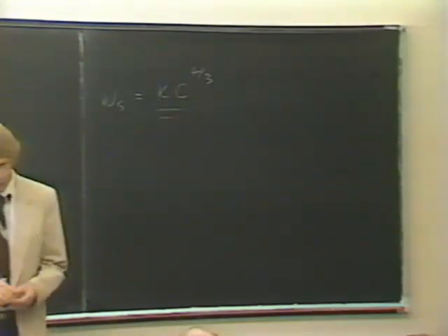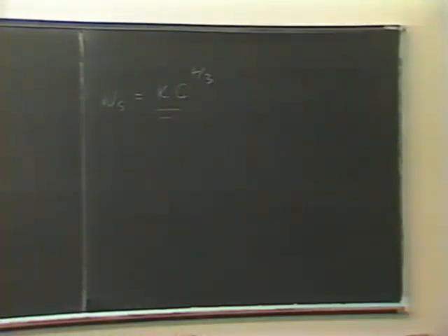And it's probably not too bad, say, in an enclosed harbor, where the breakup of the aggregates by the high velocity gradients near the bed is not a significant factor. But out in channels where the velocity gradients are pretty high near the bed, then you get breakup, and the settling velocity is not a simple function of concentration like that. It changes with the velocity gradient.